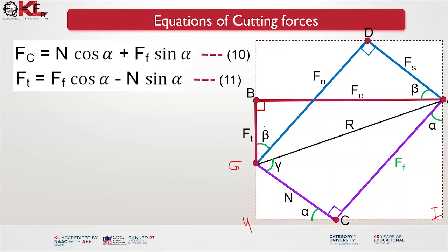And for Ft, again consider this side: Ft is equal to Ff, the frictional force, into cos alpha, minus N into sin alpha. This is equation 11.